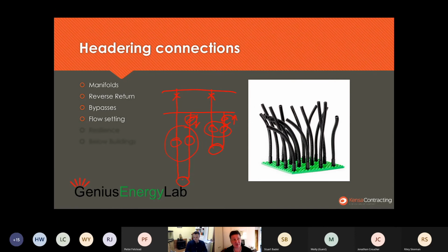So we'll tend to flag up, yeah, we're going to need some flow setting in this, and it's a little bit painful, but you're trying to get equal flow between the 2 bore fields. Okay, absolutely can't be done. Many manifolds are supplied without flow setting, just isolation valves, but many manifolds have got flow setting, and some have actually got flow meters in there. So the simple type of a meter you might see in an underfloor heating manifold, where a little bubble gets pushed up on a scale with the pressure in the system.